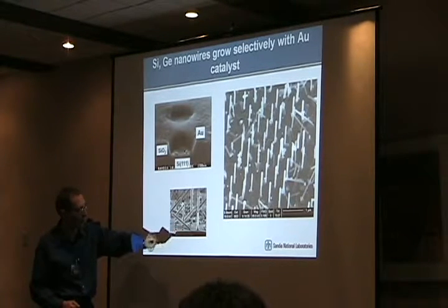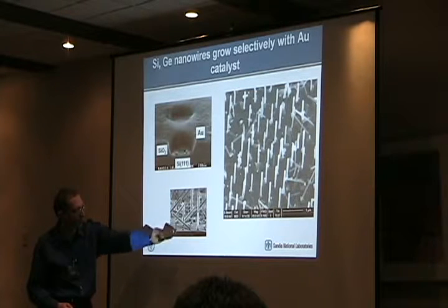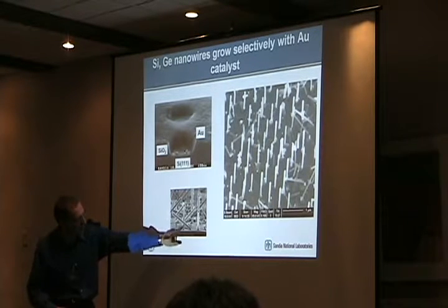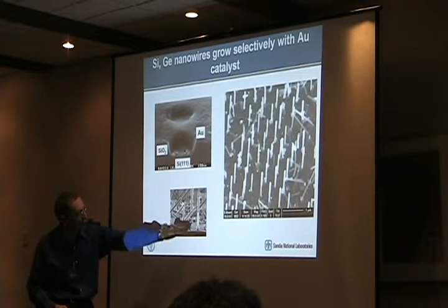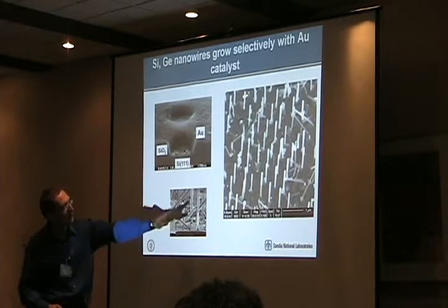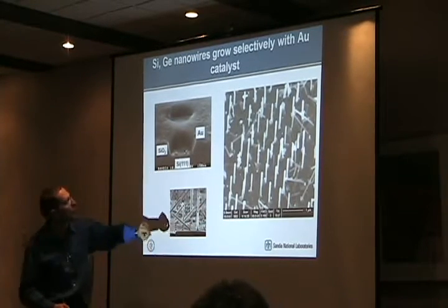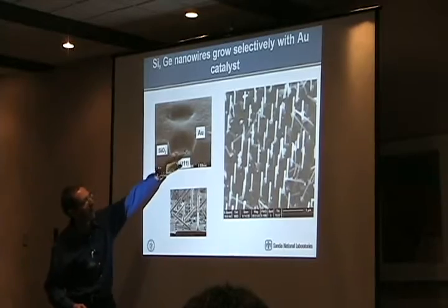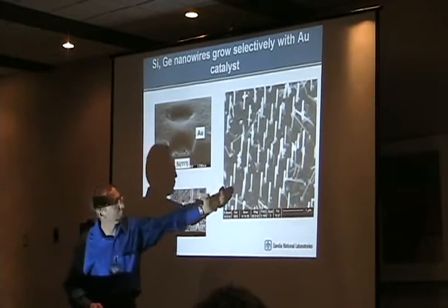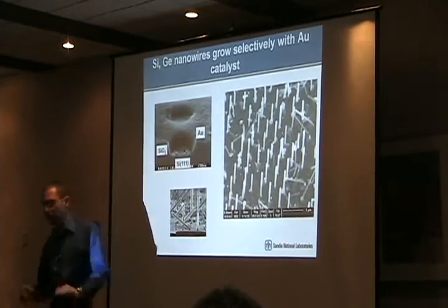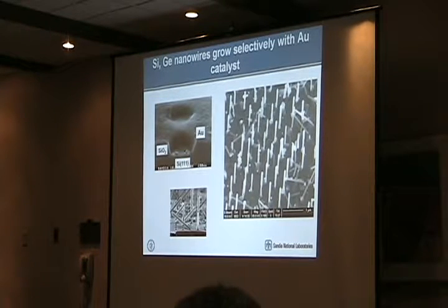You don't see nanowire growth in every catalyst, but generally it is where the catalyst is placed. And the nanowire diameter, you can see how the catalyst balled up, is very reproducible, as well as in this case. In this case, what we did is put catalyst metal inside of a well, and you see a very narrow distribution of nanowires. Now, this is in the case of silicon and germanium, so we use silane and germane